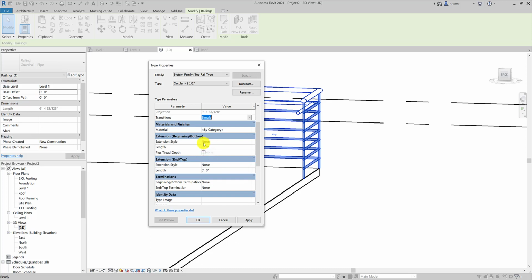If this is the bottom of a stair coming down, you typically want it to have a 1 foot or at least 1 tread width of length beyond to get it up to code. So I could add that so it's gone beyond. And then I would probably want to do it here.